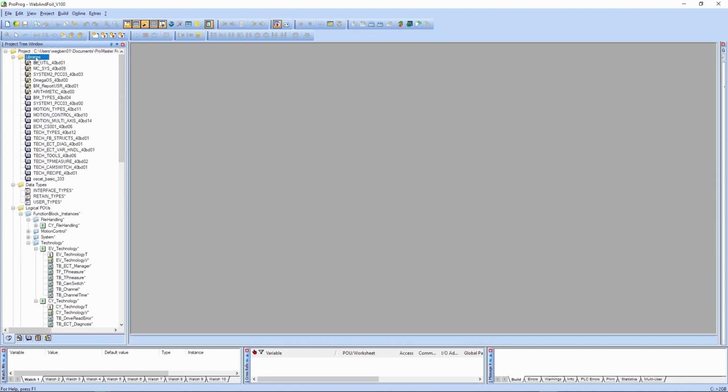First of all, we have the libraries section where you can find all the function libraries included. These yellow looking libraries, or books, let's say, are just firmware libraries, and the blue ones are the user libraries. The firmware libraries just offer firmware close functionalities. For example, reading, writing files, talking to the PLC system, getting information out of the PLC system. And the user libraries are on top of the firmware libraries, and they can be used for anything because they sometimes also use the firmware libraries.